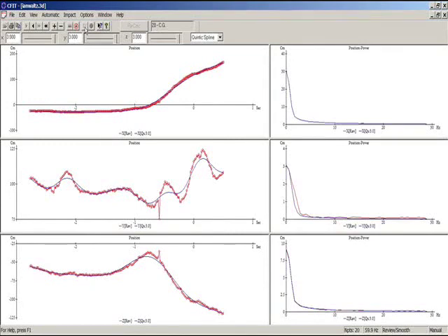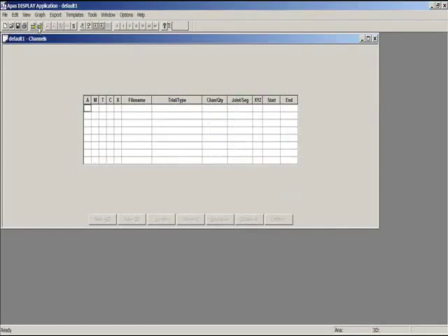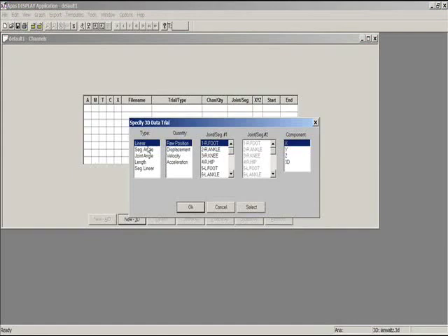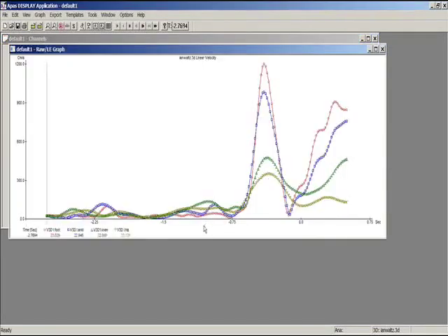So that's the end of the filtering, and now we can go back to the display to see how it affects the display. So I will stop it here, go to the display, select the data that I just smoothed, and this time I see a lot of data here: linear, segment angle, joint angle, length, segment linear. In this case, I'll take the linear velocity of the Discus and a few other parameters, like the left foot, left ankle, left knee, and left hip. And I'll do it in 3D. Now we have the 3D because we filtered the data. And if I plot it, here it is.